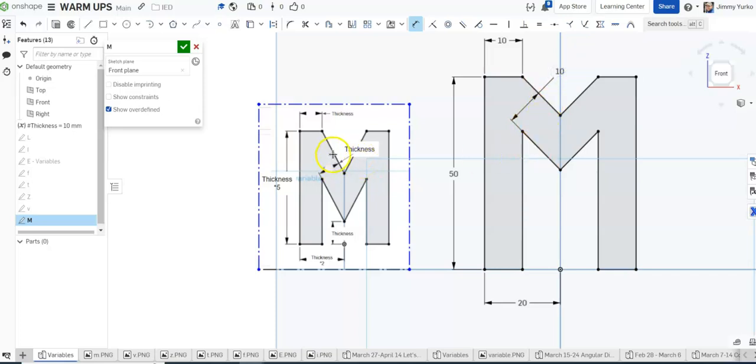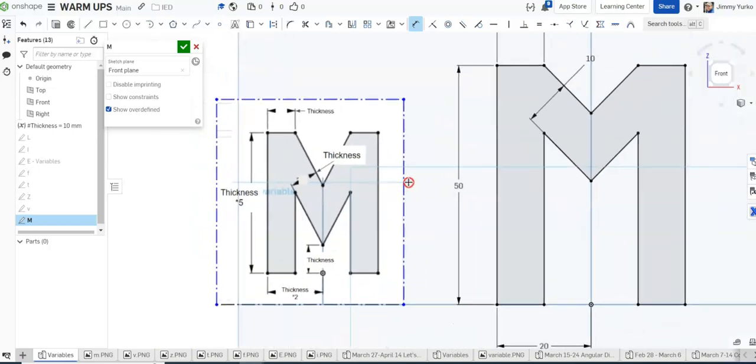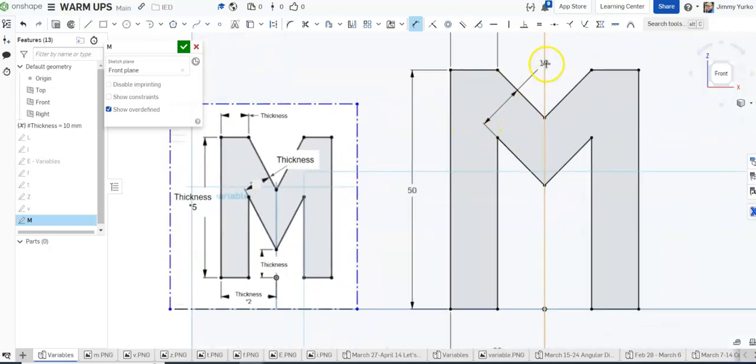And we know that these two lines are parallel because these dimensions are just numbers or numerical straight line. There's no degree symbol. If this line and this line were not parallel to each other, the instructions would give us an angular measurement to represent the angle between the lines, not the length between the lines.